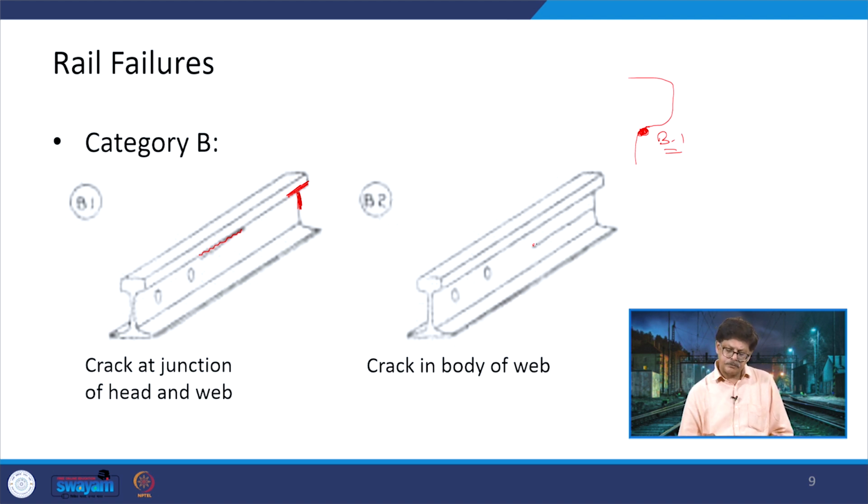If you look at the crack in the body, this crack in the body is moving here in this rail. So, it is away from the rail end, but then it can propagate maybe in the rail like this, or it can start coming towards the bolt.